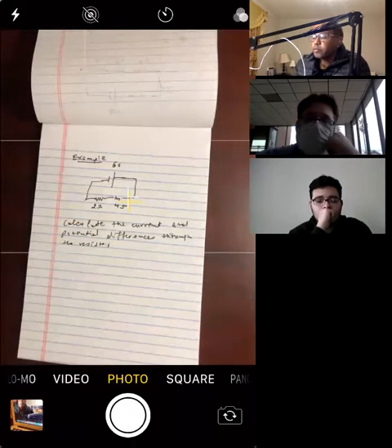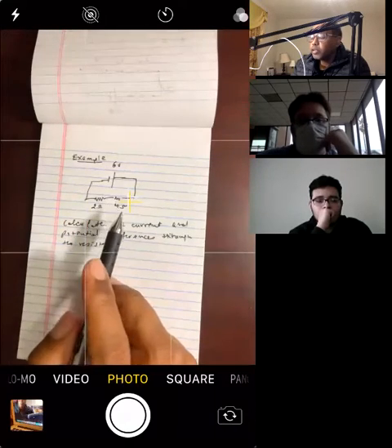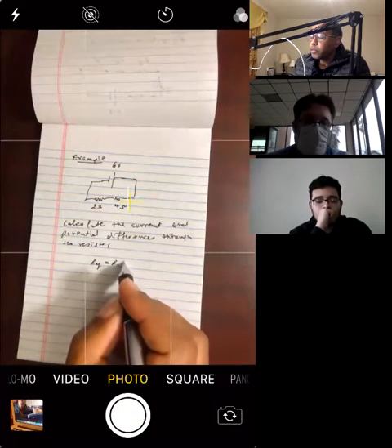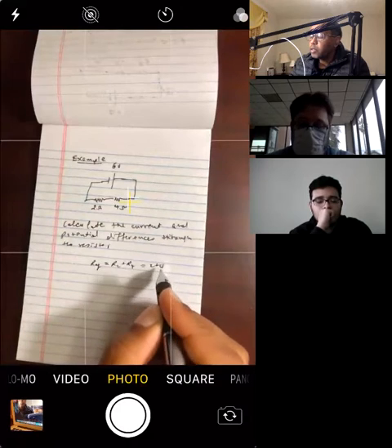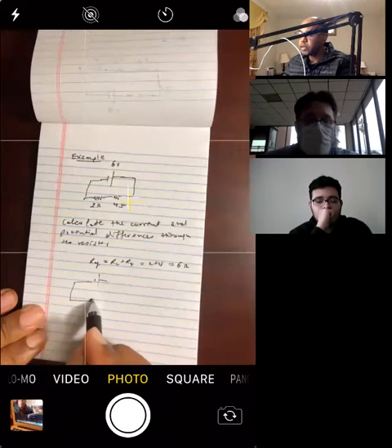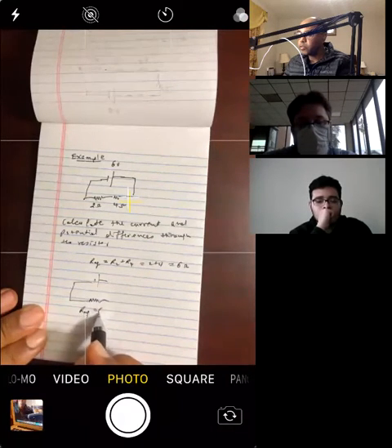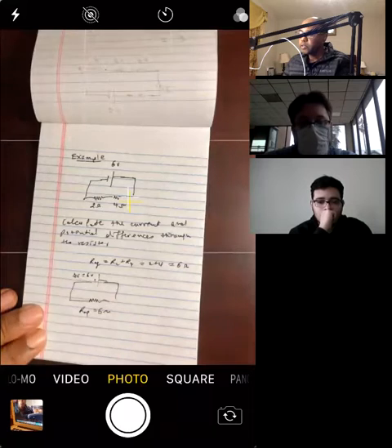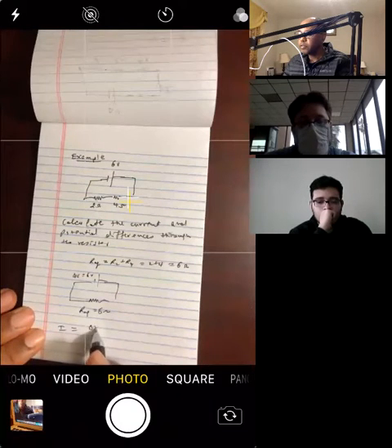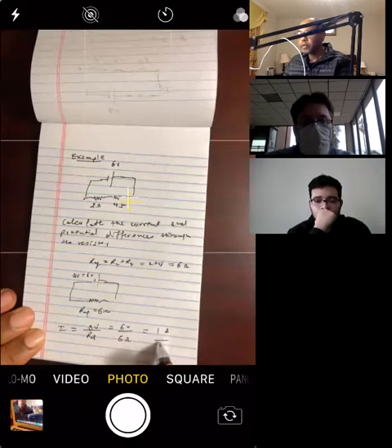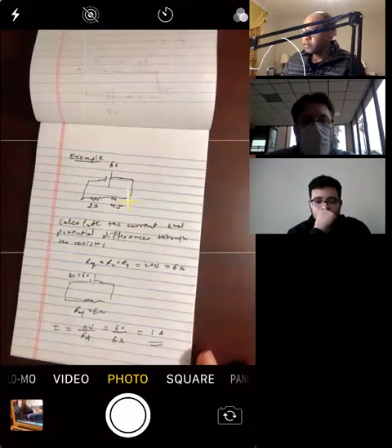So we're going to simplify the circuit. We can combine these two by calculating the R equivalent, right? So R equivalent is simply the sum. So this is R2 plus R4. That is 2 plus 4, that is 6 ohms. So we can simplify this circuit as follows. We replace that one with Req. We have Req equals 6 ohms, right? And then our potential difference is 6 volt over here. So the current is delta V, the total potential difference, divided by Req, right? So that is 6 volts divided by 6 ohms, and we get 1 amp. Okay, so the current in the circuit is 1 amp.